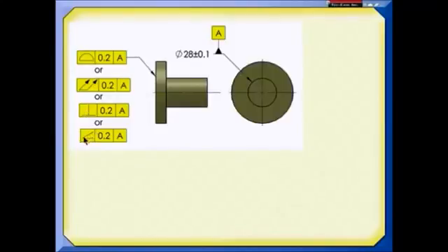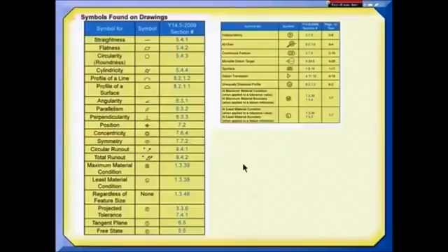However, whenever I see that angularity tolerance, I start looking around the drawing to see if someone slipped in an 89.9-degree basic angle someplace. So there is overlap in the geometric tolerances, and in this case, I would have several choices. We have 14 geometric characteristic symbols in the Y14 standard, and then with the modifiers, it takes us up to about 25 symbols, which I think is just about right.